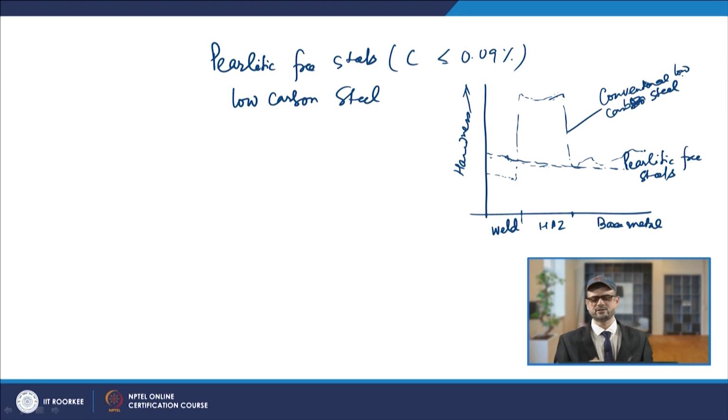This hardness can be of any scale, maybe Vickers hardness or so. So you will have about 300 or 280 on that scale. What it shows is that some of the steels are more prone, or more sensitive. In the HAZ normally you will see larger hardness, and in some cases the hardness is not at all altered.